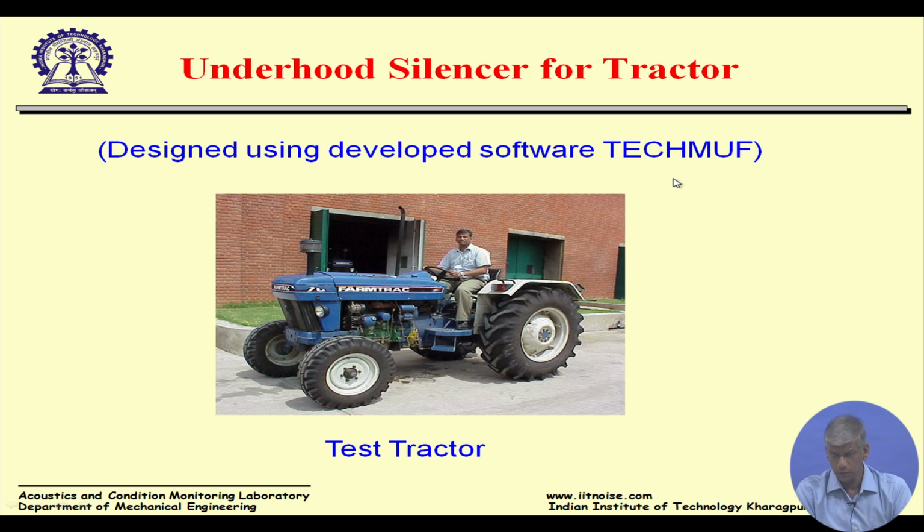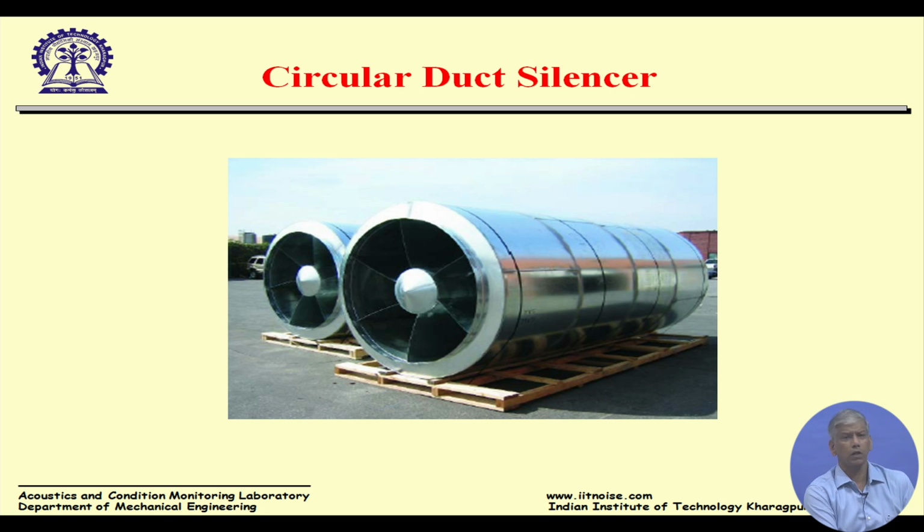This morning, Professor Bolton was mentioning this transfer matrix approach to find out the transmission loss, etc. of these mufflers, and that's a one-dimensional theory. If you look at the handbooks, you will get the matrices of different muffler elements. You could perhaps multiply them and make your one-dimensional muffler analysis, and it works pretty well. Circular duct silencers are used in many of the flow cases wherein the pressures are very low, and these are all people use in the industry to reduce the environmental noise pollution.